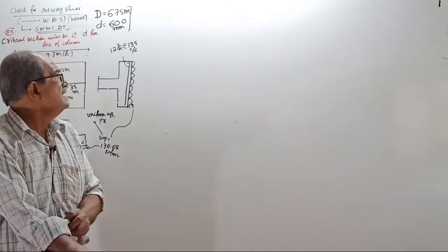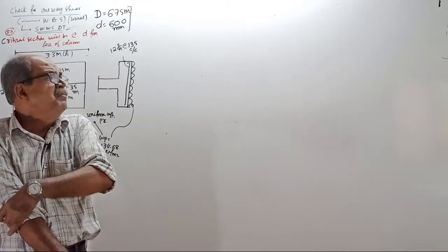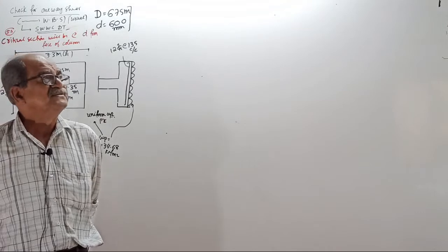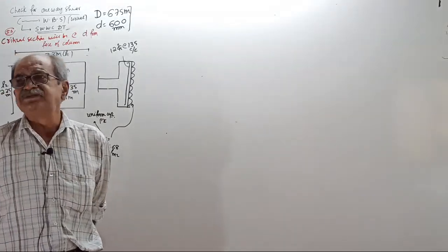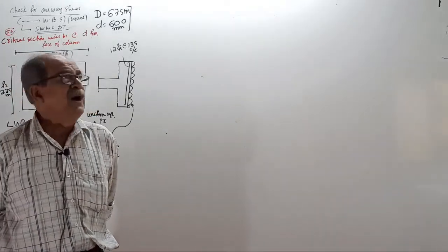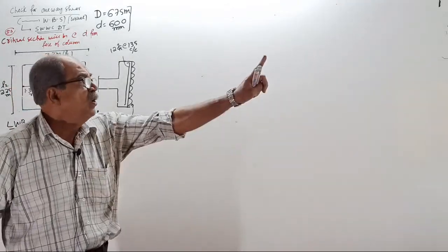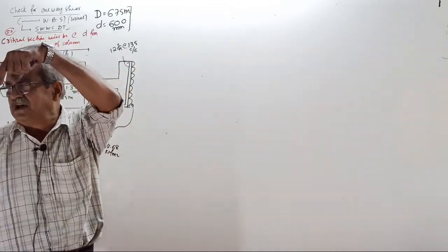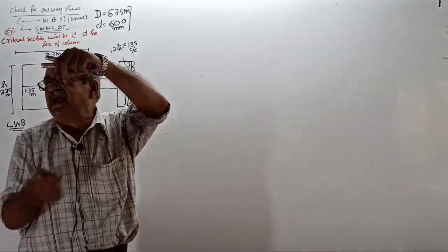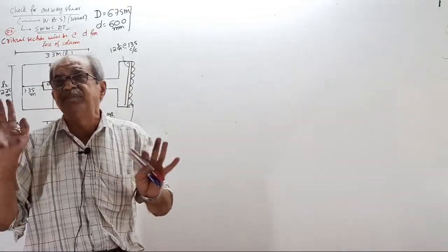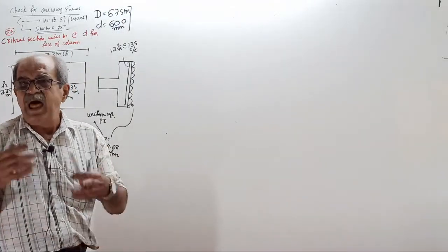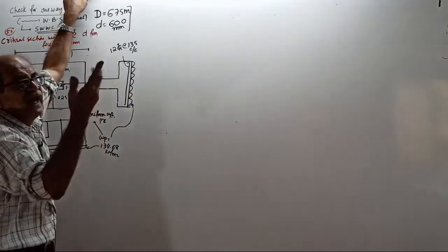This all I told you, money matters. But this idea should naturally come. When someone asks me, a column is there, effective length is 6.28 meter, shall I take 6.5? I tell, what purpose? Design. Okay, take it. Somebody wants to construct a column. He will ask me, the column I have constructed, I am increasing the floor height. It was earlier decided that column height is 3.5 meter, now I am making it 3.8 meter. I told, no, you cannot do it, danger. During design you considered 3.25 meter, now you are increasing the column height to 3.8, danger. But if the column height is 3.38 meter or 3.5 meter and when you design you take 3.8, safe. For this, you don't have to think. It should come naturally. If you have to think, then you do not know the concept.